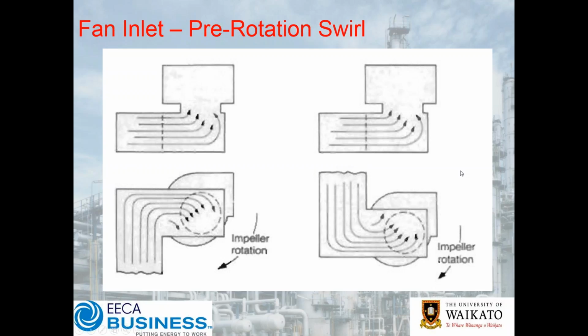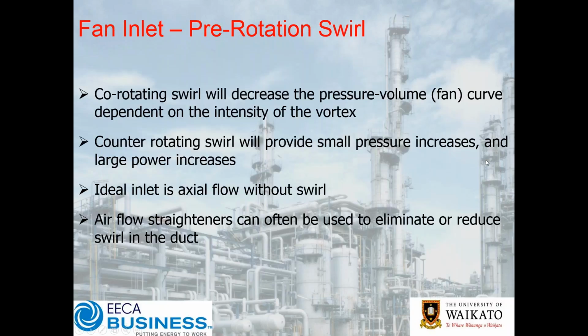So these are the sorts of things you have to be very, very careful about. From a troubleshooting point of view, if you've got a high vibration around your fan, or the ducts seem to be moving, the first thing to start looking for is the orientation of the duct and try and visualize, well, where's the air going, what's it trying to do, and is it actually working with or is it fighting against the system.